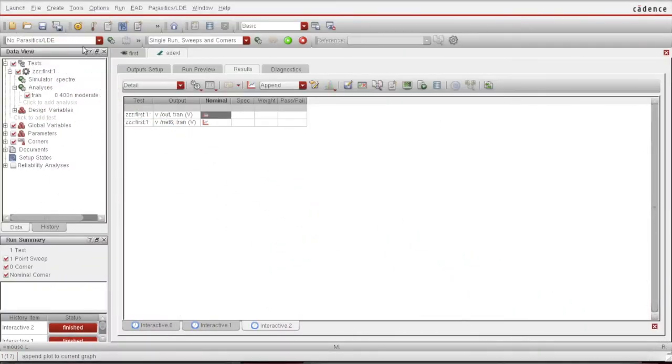Today you also learned how to use the ADE XL. It's a bit convenient. We can see the schematic and the simulation setup side by side, and we can add things into it and run it. Although both are the same, I feel this is convenient.